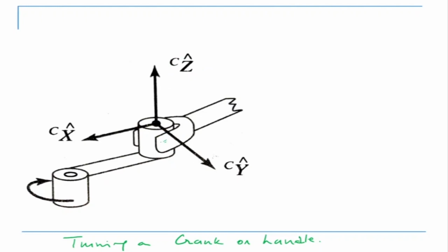Okay, now what would happen is, because of this itself, there would be natural constraints and artificial constraints. What are the natural constraints? The moment you hold it there, you put your finger, when you hold it, there are two grippers on two sides. Okay, you're holding it there. Now what are the natural constraints that have automatically come into picture? So Vx will be equal to 0. That is my x direction. So the moment you're holding, you cannot move it in this direction, right? Because it is constrained there. Okay, so Vx is equal to 0.